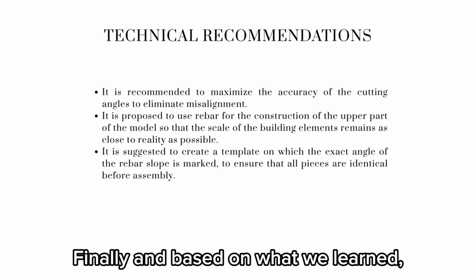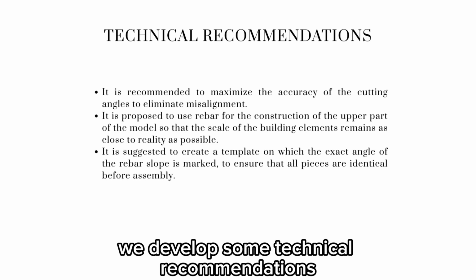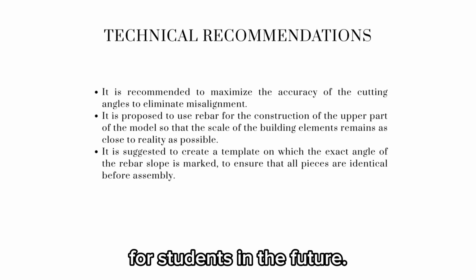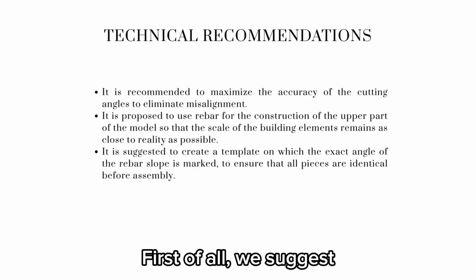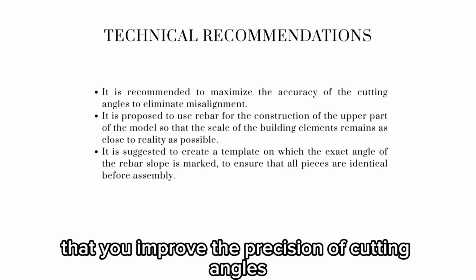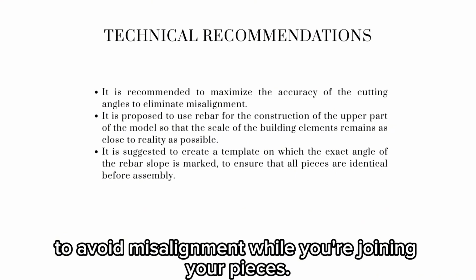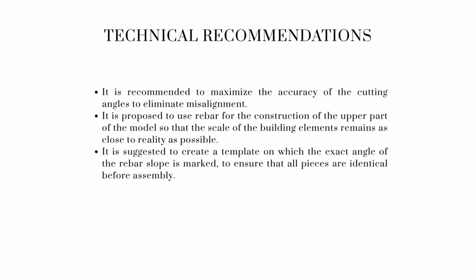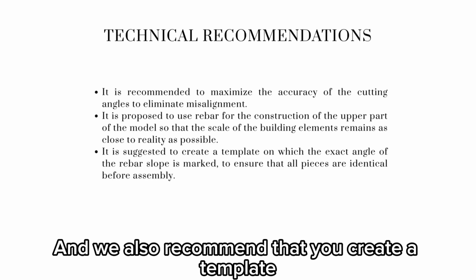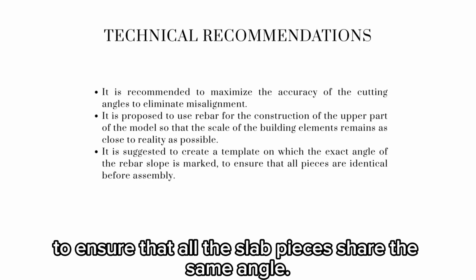Finally, and based on what we learned, we developed some technical recommendations for students in the future. First of all, we suggest that you improve the precision of cutting angles to avoid misalignment while you're joining your pieces. And we also recommend that you create a template to ensure that all the slot pieces share the same angle.